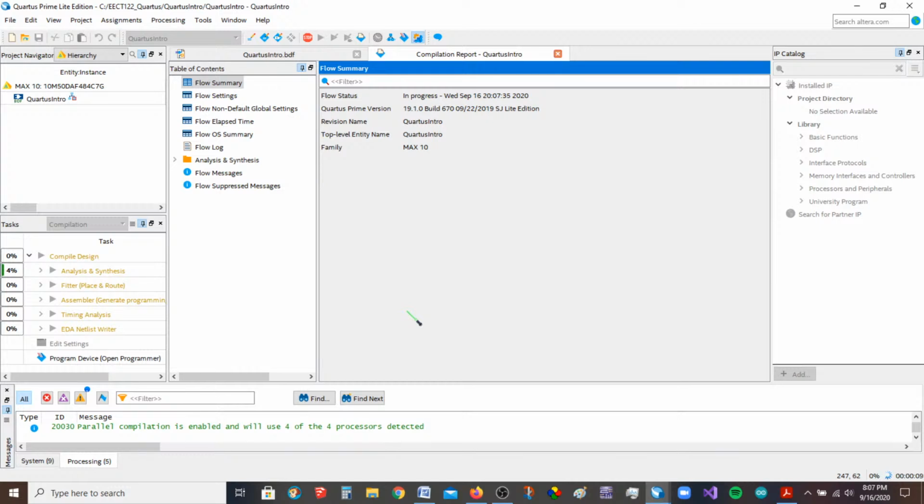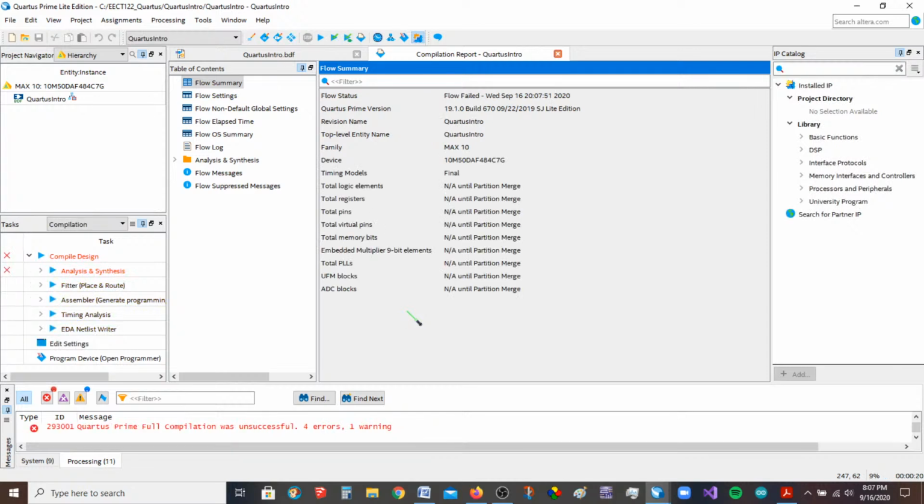And we'll let this compile, and then we'll go see what it looks like in a vector waveform file. And I'm probably just going to use the one I used before, but I'm going to have to do some work to it. Oh, doesn't like something I did. What doesn't it like? Let's see here. I'm glad this happened. Okay, so I'm going to scroll up here to my errors. Can't elaborate top levels. Oh, okay. I'm glad this happened. So glad this happened.